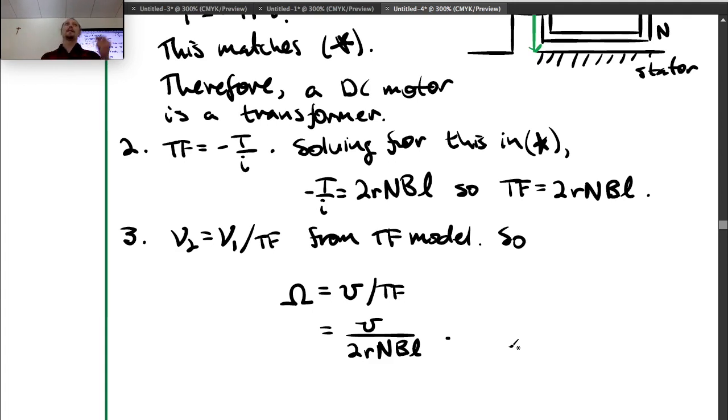So it's not just your motor you have to think about. It's how much power you can supply, what situations you might run into where you have a stall, and how long you can be in that stall. Because heat is something that dissipates, but it dissipates slowly.